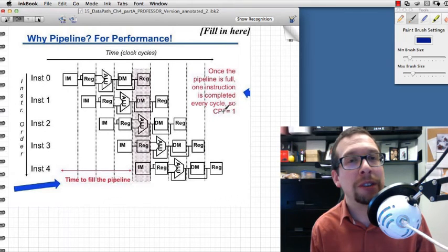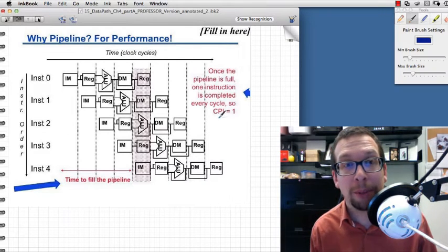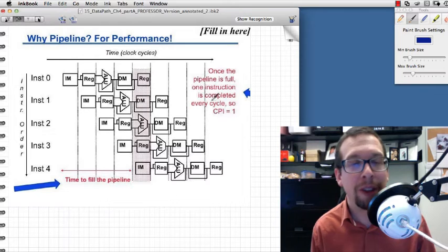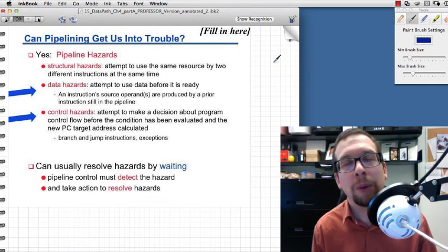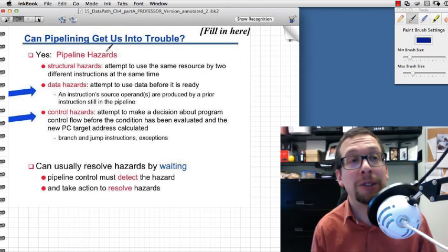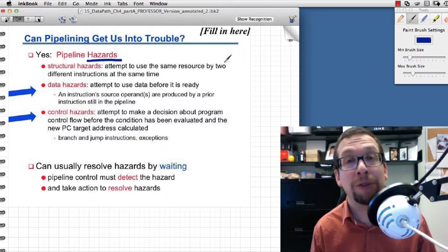So the cycles per instruction becomes 1 once that pipeline is full. If the pipeline blocks or needs to be refilled, then that complicates things. So we typically think of the best case scenario, but in the event that there is something referred to as a hazard, then you may have to flush the pipeline or modify the pipeline or something like that.